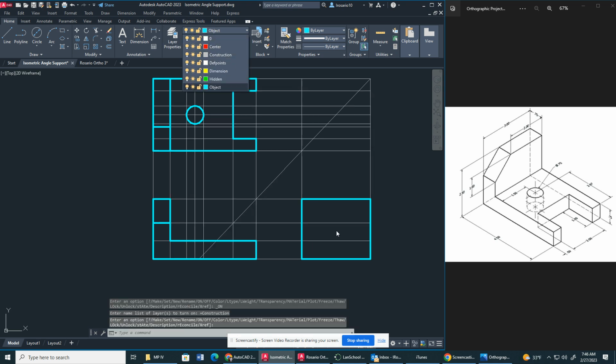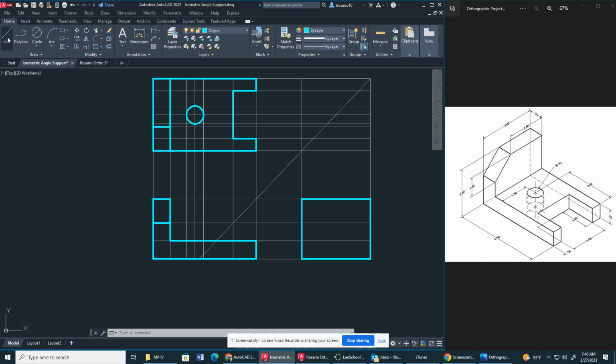Now, I'm going to create this one right here. So if we're looking at it from the top view, right? I'm sorry, from the right or side view. I'm going to offset this line right here by 2. That's going to be our change of depth, right? I already have this line here from 1 because of this change of depth. Now I can just draw the angular line from this intersection point to this intersection point, okay? I also have to highlight this right here because we have the 0.75 inch thickness.